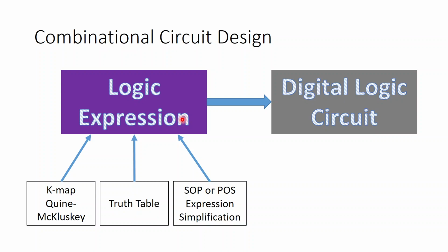And we also know that sometimes we can be asked to use only NAND gates or only NOR gates or only AND OR gates. So if we have certain constraints, then we have to manipulate this logical expression in such a way that we are only working with those logic gates which we are given. So we know we can do that sort of manipulation.